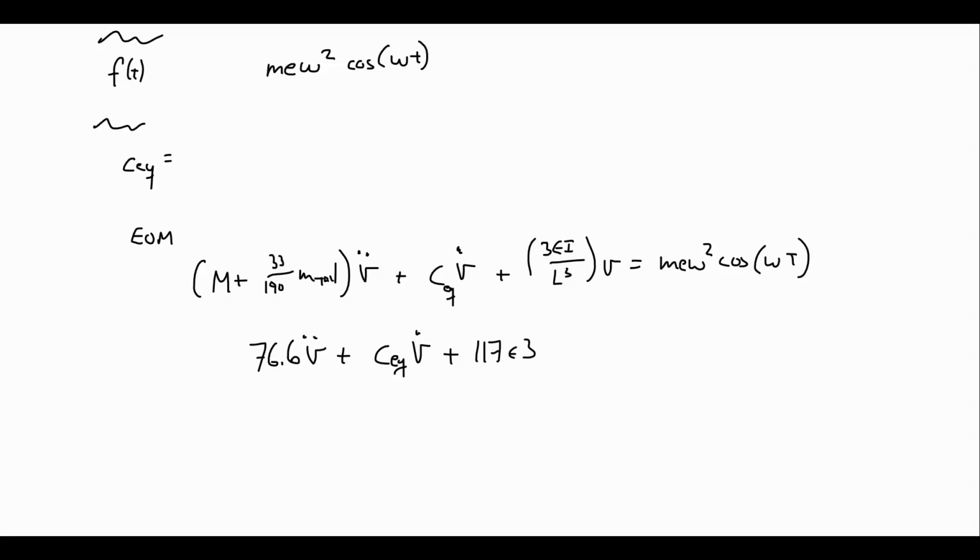So again, I will just operate in base units here. And now we have that eccentric mass that had a mass of 0.5 kilograms. And we were given that the eccentricity was 0.15 meters. And we have an angular velocity of 1500 RPM, or 157 radians per second. And we'll revisit this in a moment, but we can put this together too. That will be 1850 newtons times the cosine of 157 t.